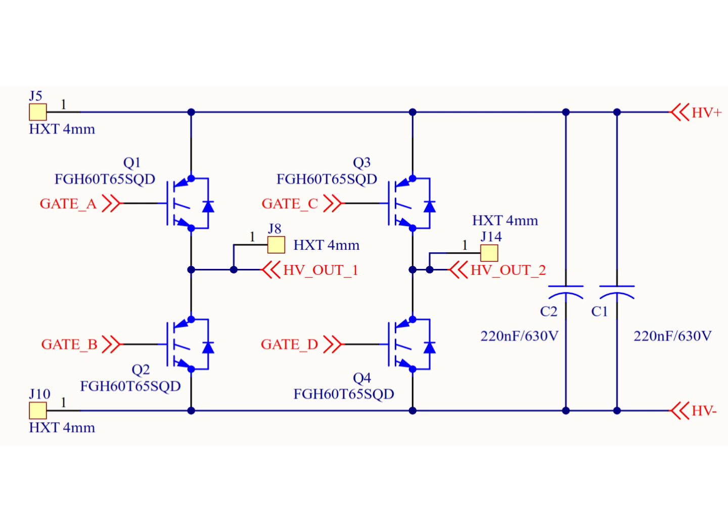A 650-volt device gives us a margin of about 1.6 times the bus voltage, which is an excellent balance, safer than a tight 600-volt part, while avoiding the higher losses and cost of a 1200-volt device.